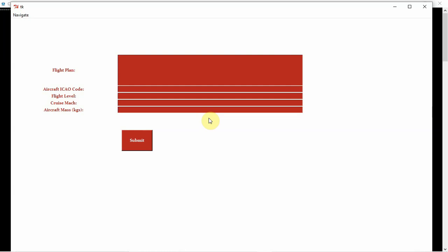The different configurations: takeoff starts with lift and drag configuration with a thrust. Thrust is the force which moves the aircraft through the air. This is generated by the engines of the aircraft. The thrust for the takeoff would be maximum climb thrust settings. Then the initial climb will have the lift and drag configuration and maximum climb thrust settings. The climb phase will have clean aircraft configuration with maximum climb thrust settings.